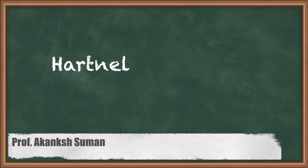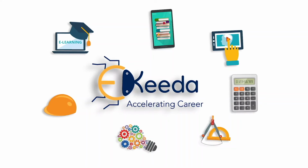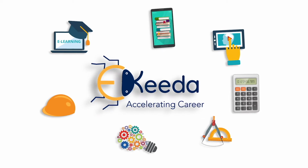Hello everyone, we are going to start the discussions on the Hartnell Governor. In the last sessions, we have completed the Watt Governor and Porter Governor as well as the Proell Governor. But this is somehow different from the other governors, because the Hartnell Governor is basically a spring controlled governor. When you say spring, there is a force, spring force F is equal to kx, which is directly proportional to the displacement.